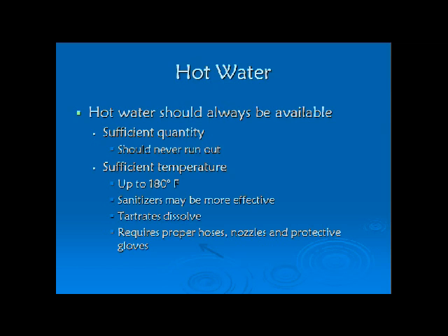But if you use the hot water on them, they dissolve actually pretty easily, and sometimes you can just hose them off with hot water, and they fall right off the side of the tank kind of nicely. Sometimes you do have to use a cleaner, and an alkaline cleaner works best on that, but you can get by with hot water in a lot of cases, as long as the water's hot enough and you have good flow rate and also good pressure.